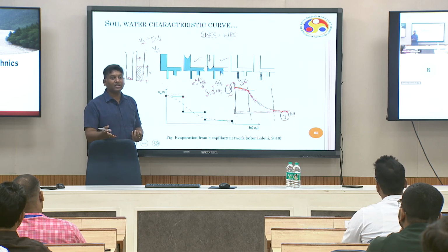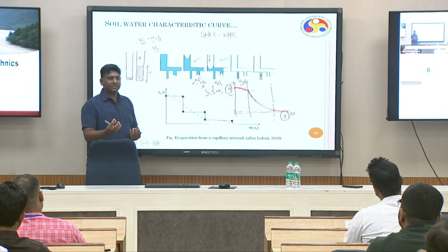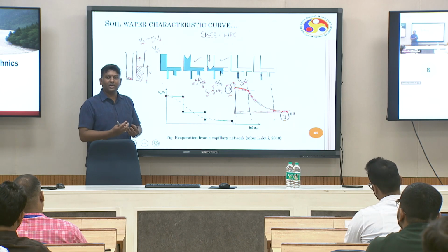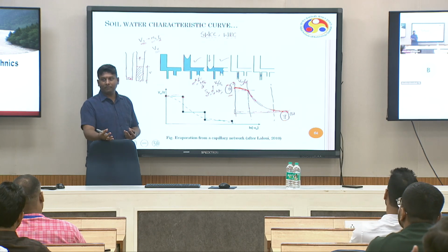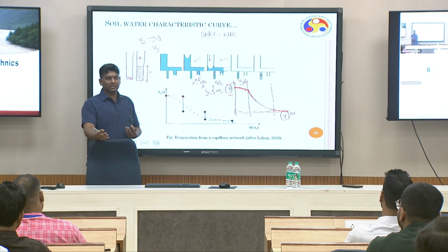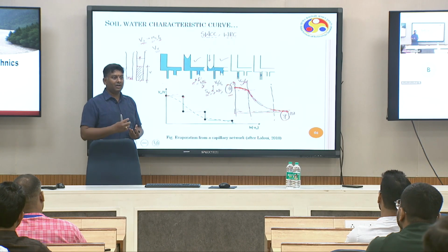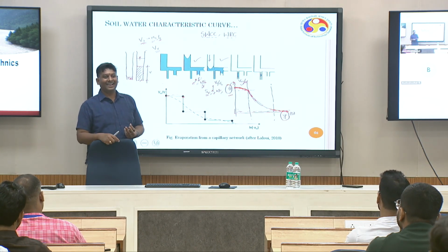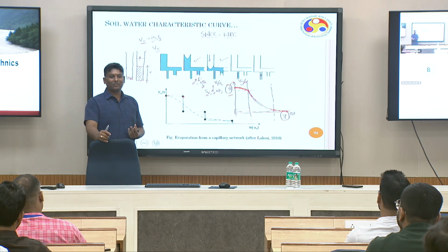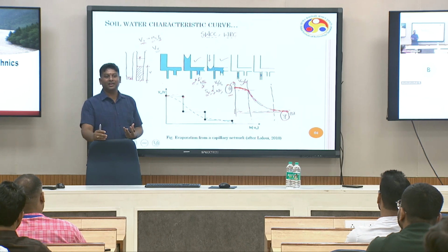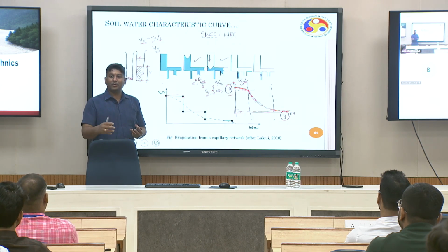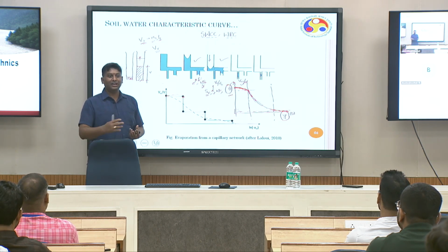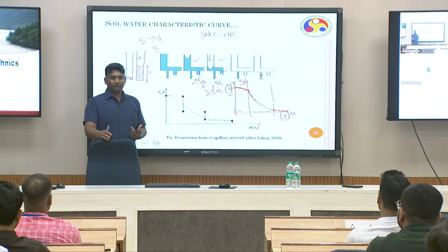That's what we do in shrinkage tests, right? In shrinkage tests, we mix the soil with water and keep it in atmospheric conditions under some RH and temperature. Then evaporation takes place. Why does evaporation take place? Why does evaporation have to take place? Because of the vapor pressure difference or the energy difference.